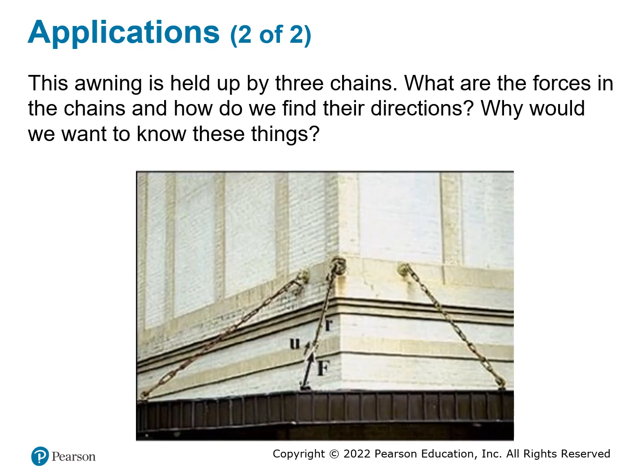Similarly, this is another example. You have an engine held by 3 cables. The middle one connects from the bottom point to the hook on the top. This is the position vector R, from the bottom to the top. If we know R, we can represent the force in terms of the magnitude of the force and the unit vector along this line, and then we can represent the force in a 3-dimensional way.